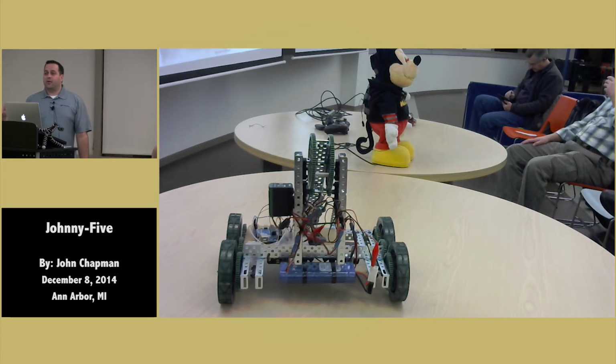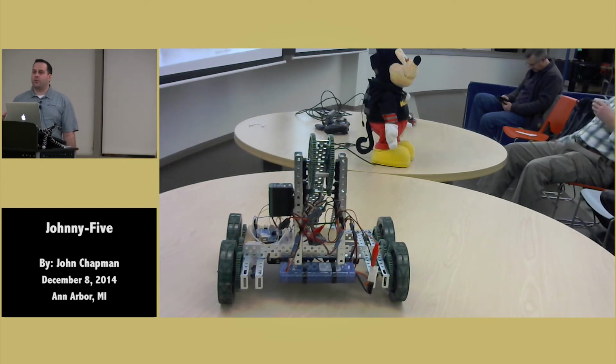The problem is the Galileo doesn't have a built-in voltage regulator, so you have to use an external separate voltage regulator to get the 5 volt input, because anything outside of like 5.25 and 4.75 volts, and you're going to fry your Galileo. So for that reason, I tend to gravitate towards the Arduino because it's so friendly to get up and running.